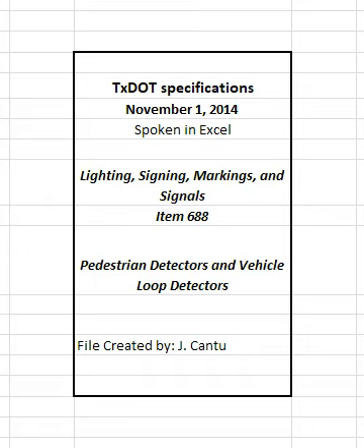The conduit and loop wire from the edge of pavement to the ground box used for the vehicle loop detectors will not be measured or paid for directly but will be subsidiary to this item. New ground boxes will be paid for under item 624, ground boxes. New loop lead-in cable will be paid for under item 684, traffic signal cables.